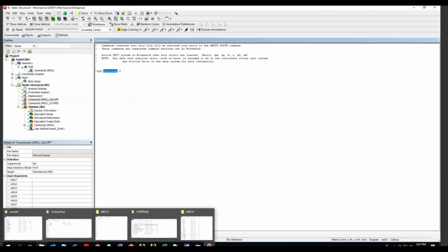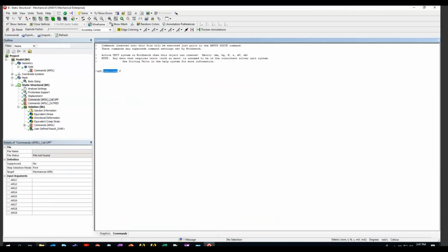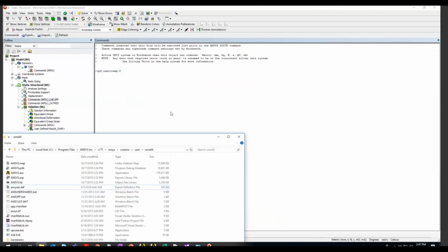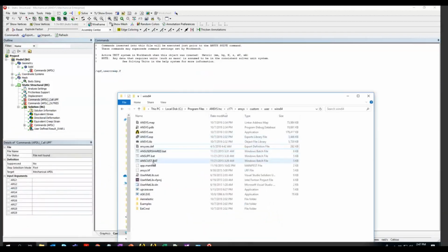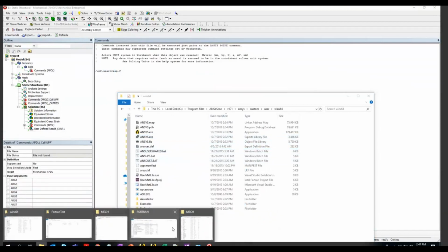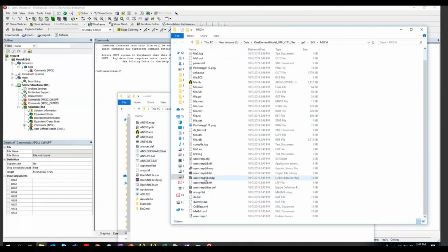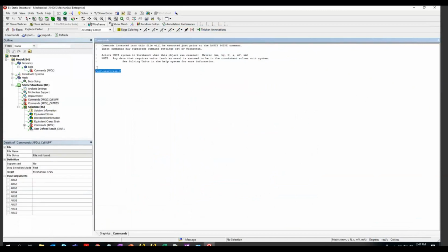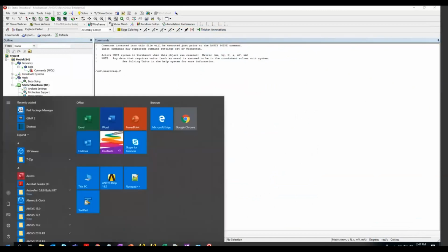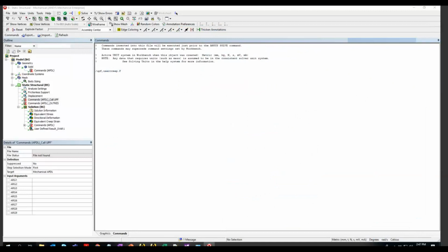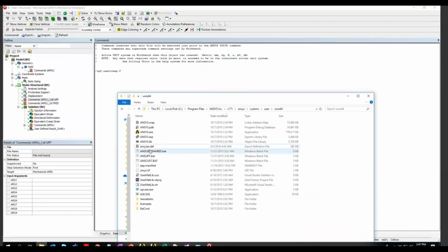We don't want to really go through the path of running this custom.bat every time. The compilation is going to happen in the background every time we run this. Okay, so this is now produced as 2.45 and so on. So the advantage of using this procedure is we can skip doing the compilation and linking through ANSYS custom.bat,